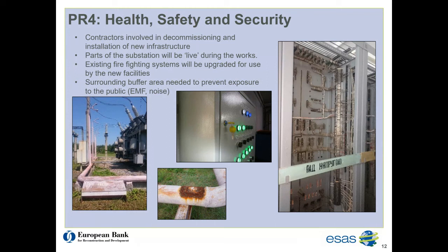Where enclosures do have locks, the keys have been routinely left in cabinets. The keys are not under the control of a competent person. Furthermore, safe approach distances and access control measures to live equipment is not specified, and there is no documented contractor management procedure. Moving on.